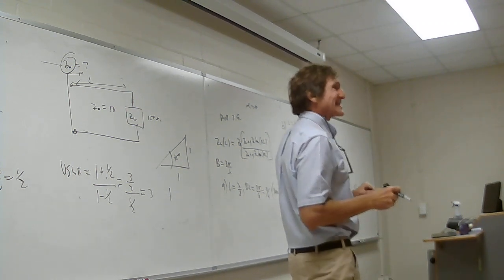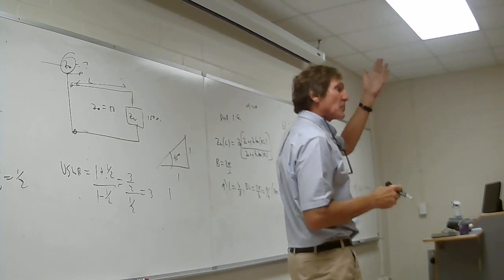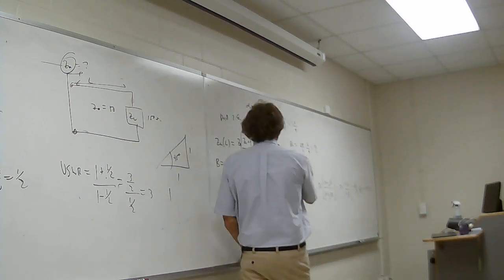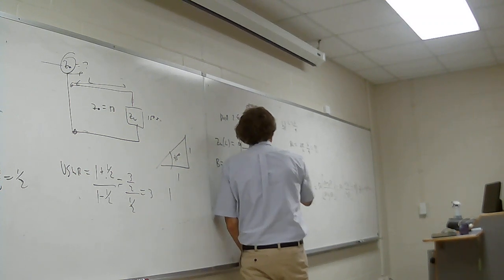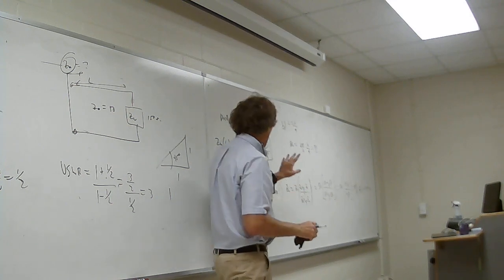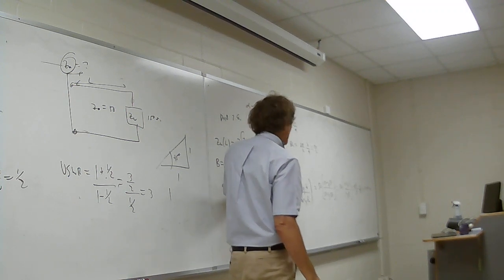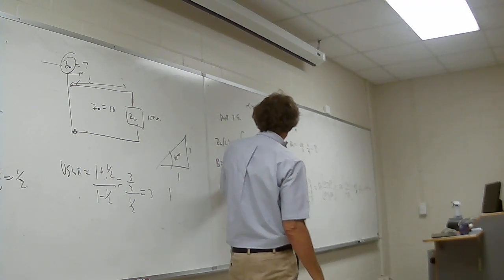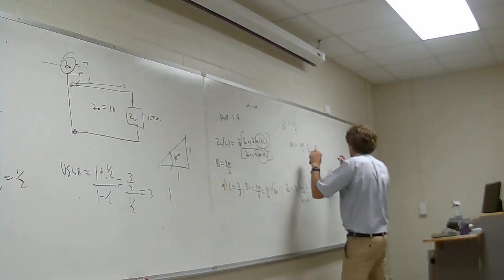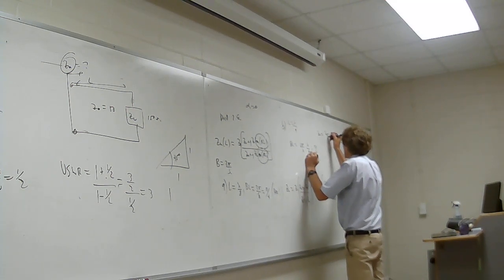Now, what is the tangent of pi over 2? Undefined. It's tending towards infinity. Here's what that means. This term dominates, and this term dominates. These two terms can be ignored, because that's going to be so big that the other term doesn't matter. In the limiting case, you're going to get Z naught times Z naught over ZL.